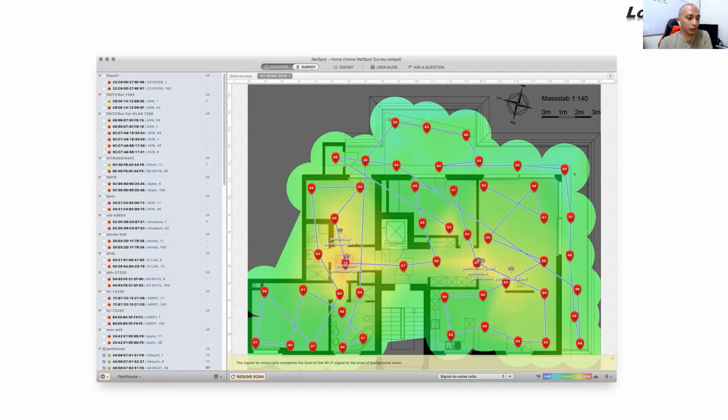So what we do on an on-location RF planning is that we go around all of the areas of the hotel, for example, then we do a wireless signal survey where we walk using a laptop or our mobile devices, and we actually measure, okay, for each location of the area, how strong the Wi-Fi signal is. For example, here, okay, you can actually measure the Wi-Fi signal for an individual location. Okay, so you can do that for 2.4 and 5 gigahertz. Okay, so that's called the on-location RF planning. But if the client really wants a brand new solution for the Wi-Fi, I use predictive, and I mostly use predictive.